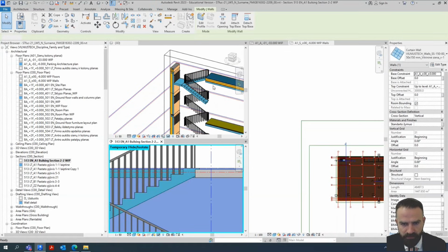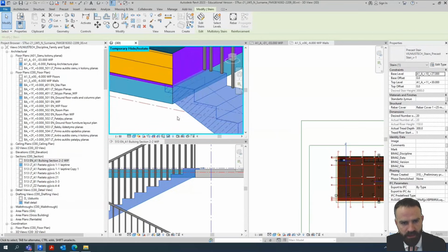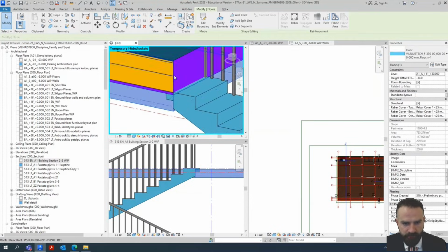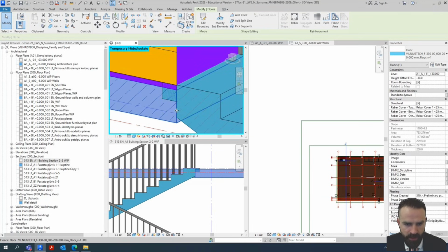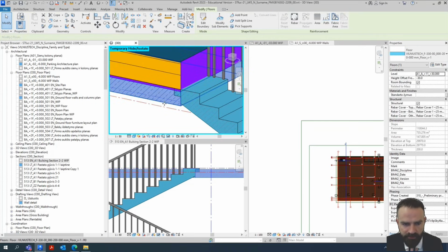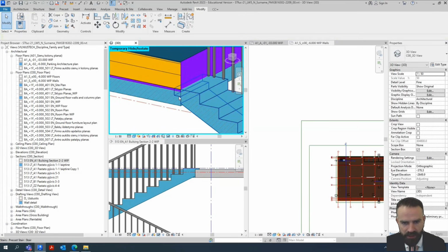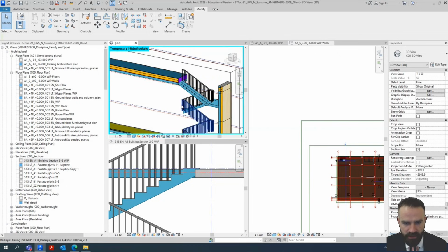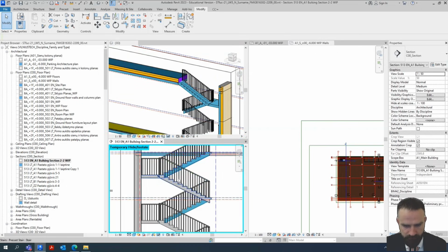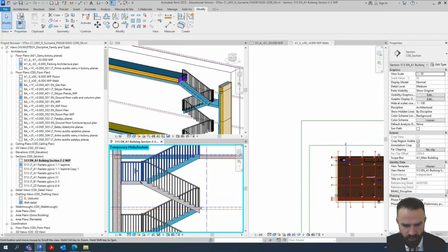So here I have a problem on the last floor, because my connection to the floor is a little bit not correct, because I have a roof configuration and I have the top floor. So in this case, my floors and my roof are at different levels, and I need to fix that. The best option is to make the same height for your floors.